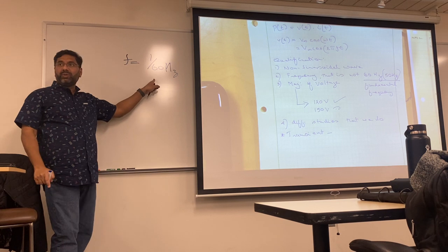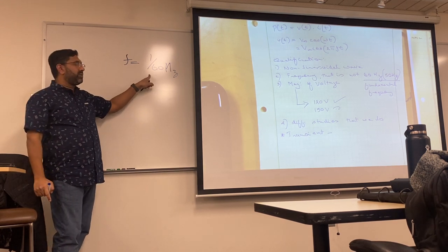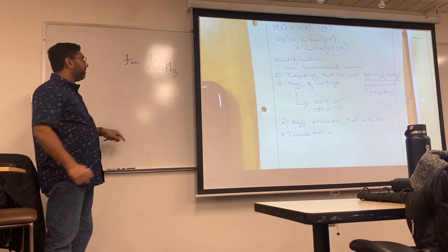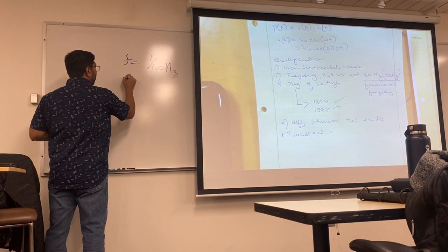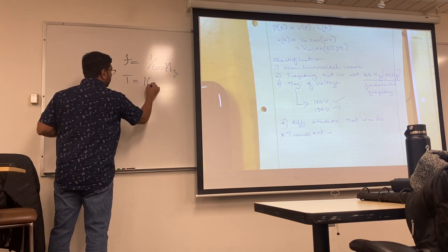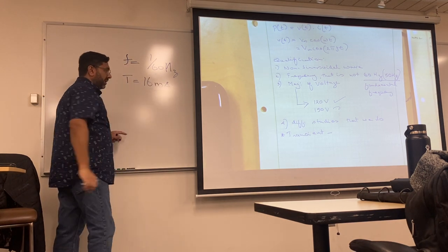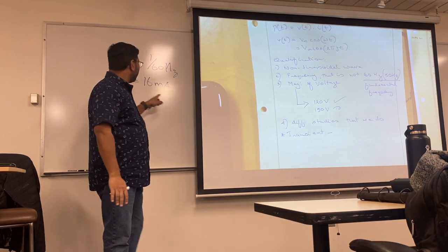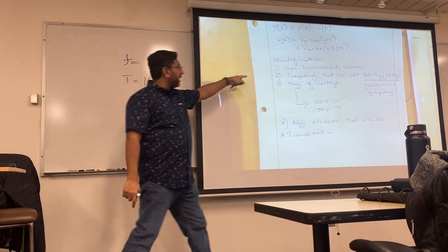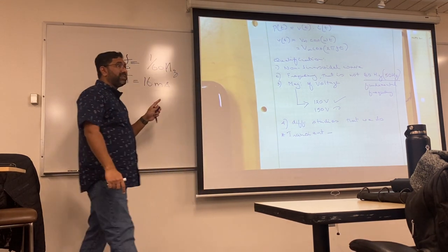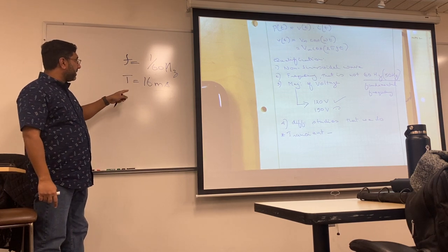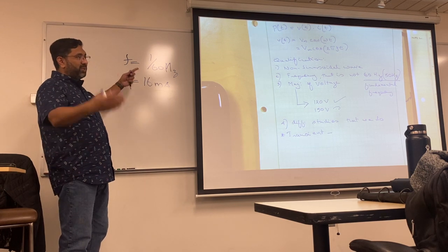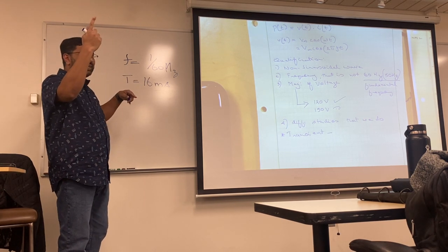This is pretty useless in our industry. You can take it for electromagnetism and give it to them and they'll be pretty happy. For me, this doesn't make any sense. For me, I have to do this 1/60 and get the time, and that's 16 milliseconds. Nice. So the only reason you guys are not seeing any of this jazz is because in 5 or 6 cycles, I am able to provide a good power to you. But for the first 5 cycles or so, it would be rubbish. And it's still in milliseconds, so your device is not picking it up. Worst case, you see a flicker, and that's even several milliseconds.